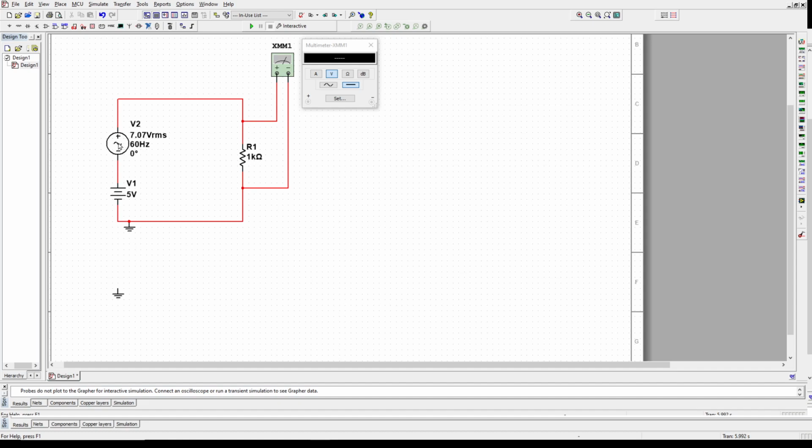It's taking the average of the AC component, and the average DC component of this AC waveform is going to be whatever is in the middle of the waveform, which means it's sitting right on top of the 5 volts. So that will be almost seen as ignored, but not. It's the average. The average DC component of this is basically 5, well, it's going to be sitting at 5 volts. Let's confirm that, shall we?